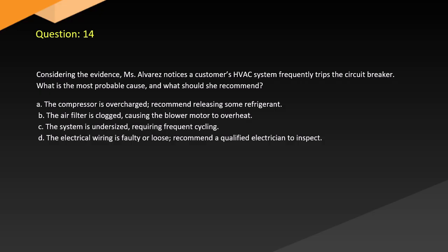A. The compressor is overcharged. Recommend releasing some refrigerant. B. The air filter is clogged, causing the blower motor to overheat. C. The system is undersized, requiring frequent cycling. D. The electrical wiring is faulty or loose. Recommend a qualified electrician to inspect.